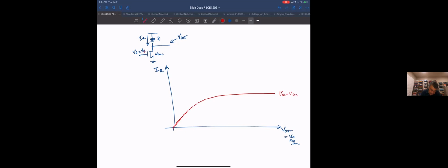Now notice, a load line analysis gives you the range of permissible currents and voltages for this device. And on top of this, I want to superimpose the range of voltage and current values for the other device. Why am I doing that? Because where those two curves intersect is the only possible solution for this VDS value.